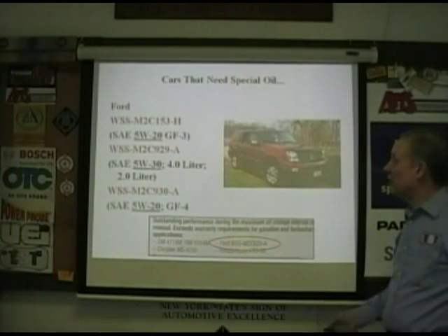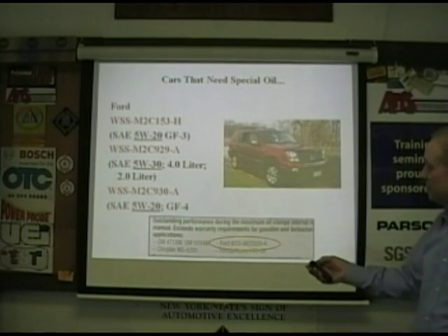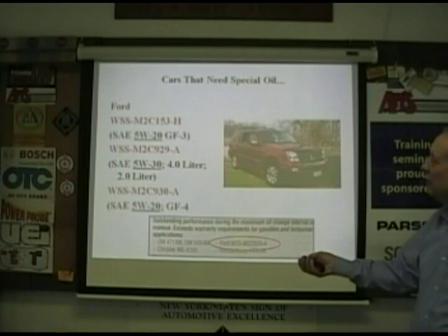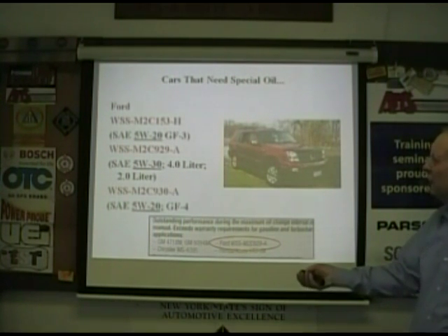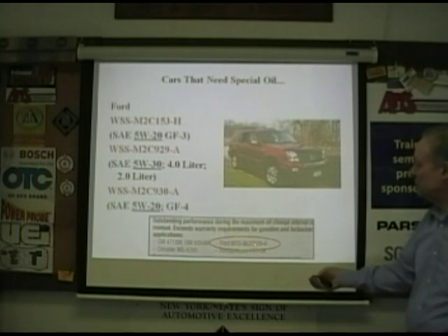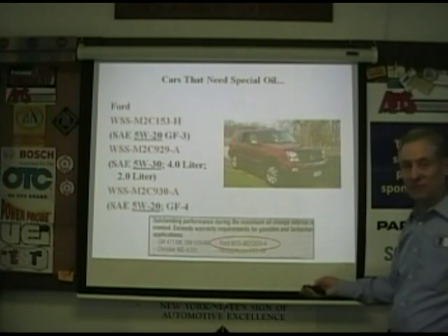All right, more cars that need special oil. Ford. As you can see, there's a few specs here. 5W20, a 5W30 for different engines, and a different 5W20. You have to make sure it meets the spec. Again, read the spec for that car, the one you're working on. Don't just say, I got Ford oil, it's good.